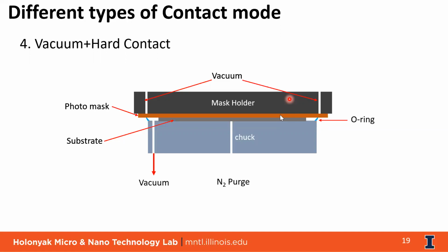But it's always a trade-off between your soft bake and the development. Sorry, if you increase or decrease your baking duration, it will have a direct impact on your development rate as well. So that's the reason we always fix the timing between these windows. You don't increase or reduce it too much.